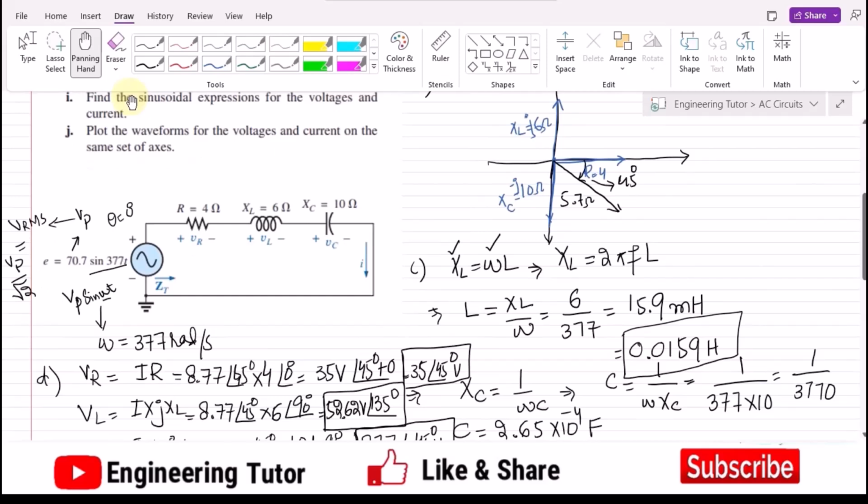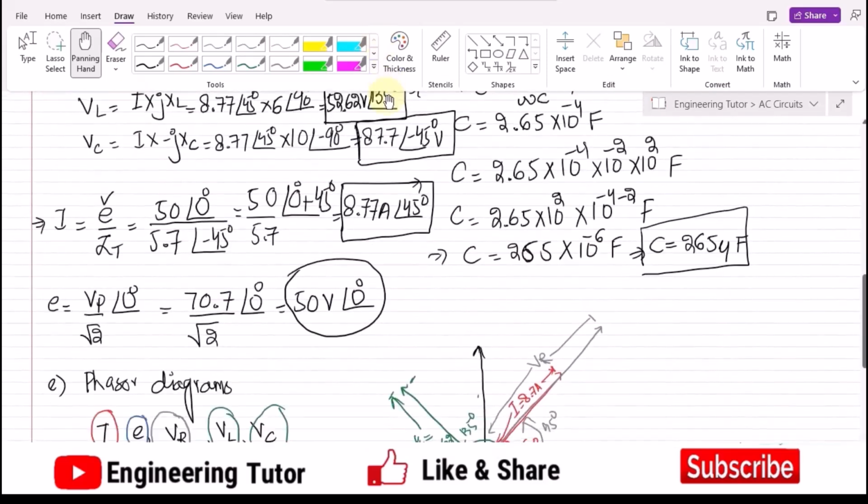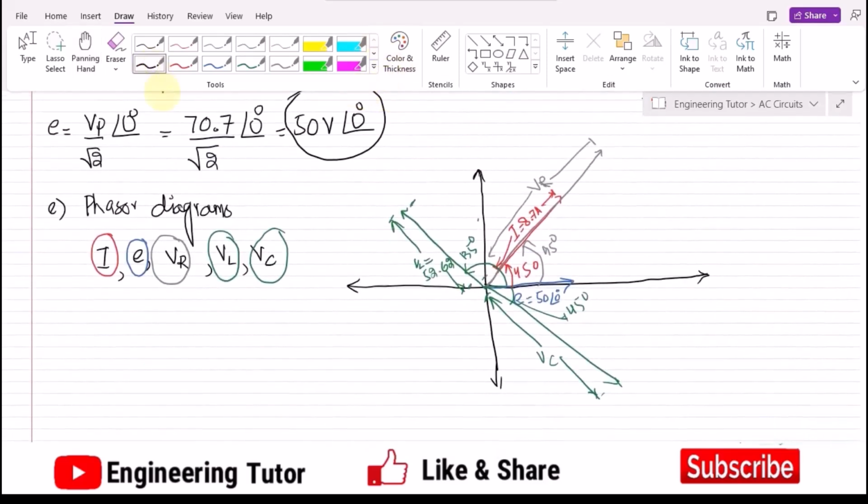So this is the closed loop, and around it we have to verify Kirchhoff's voltage law. In order to verify it, we have to see whether the total voltage E is equal to the phasor sum of V of R, V of L and V of C. So the phasor sum of all the voltages should be equal to the total voltage or not.